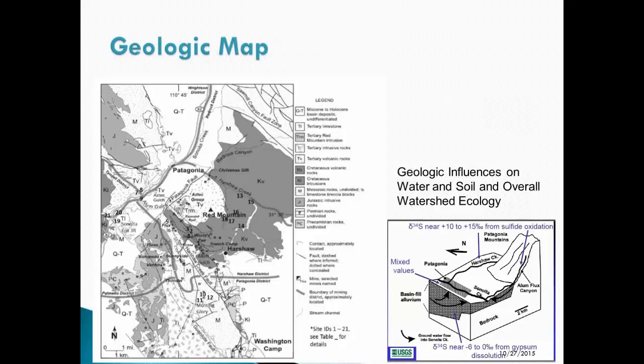The geology of the area was such that it wasn't really acid mine drainage as much as it was acid rock drainage. The big porphyry had come up into the area, and whether or not mining had ever been done in the area, the water going through those drainages was going to be very low in pH.